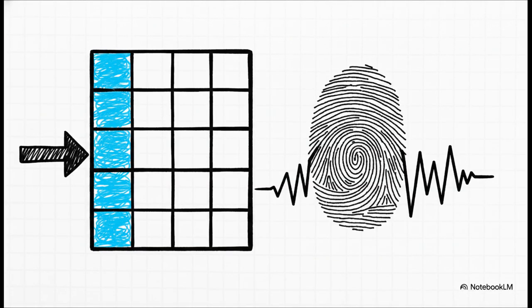row right above it. And here is the absolute most brilliant part of the Routh-Hurwitz method. Once you've completely filled out the entire matrix all the way down to the bottom row, you get to ignore almost all the math you just did. Seriously, you look only at the first column. The rule is incredibly simple.